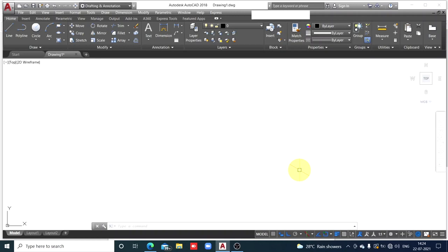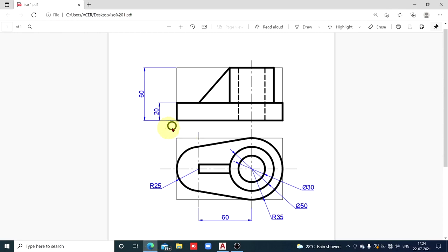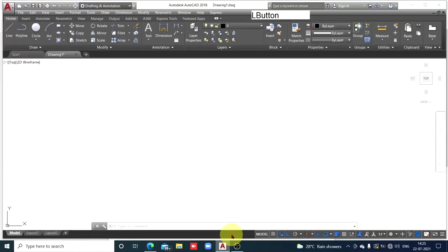So vertical, that green hairline, that is the height axis, and that red hairline is the width axis. I am sure about that, because in orthographic views, watch here, in this orthographic view, point O is on the left side. So the left axis, inclined at 30 degrees in this orientation, that is the width axis. Okay. So here only two axes right now are available. Which two axes? Width axis and height axis. But check what is there in the drop down menu.